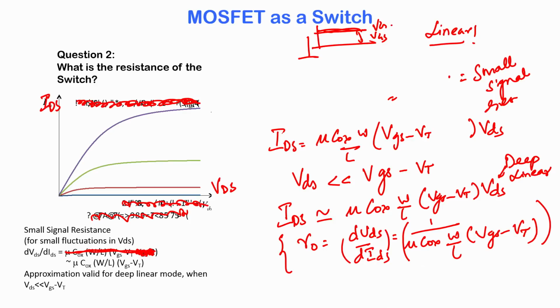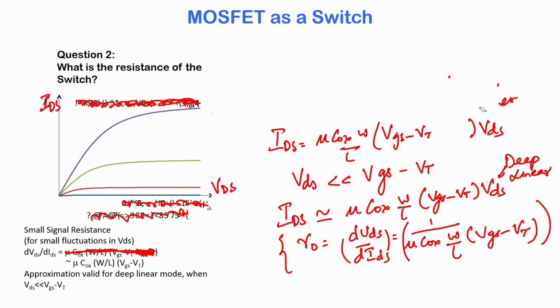So let us now play this game of connecting all these properties to our understanding of the device physics. Let us see whether we can use this as a refresher for your device physics. Now, as a circuit designer, you have identified that this is the small signal output impedance of the MOSFET when it is in linear mode operation. So, firstly, does it make sense?